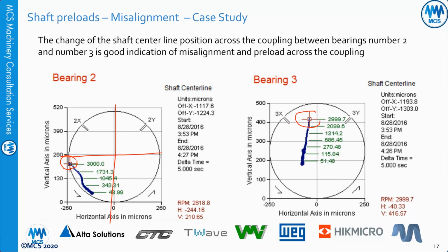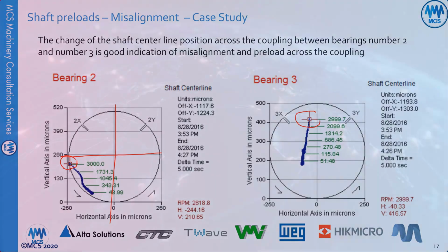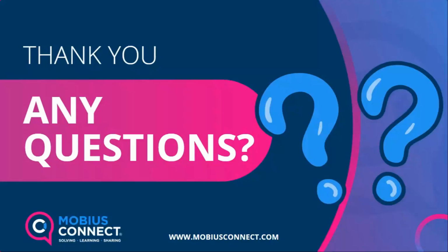I don't think so. This is something you need to check anyway, like the lubrication. For example, I have one of my customers' power stations, and every 3 months we check the oil for 4 big turbines, 375 megawatt.